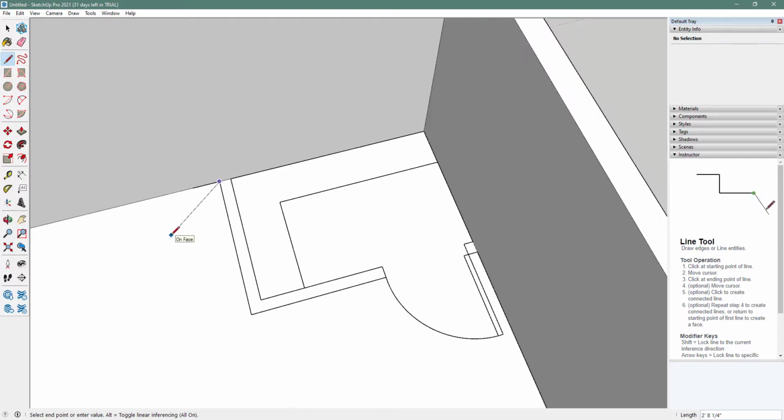That means you've started the line command, and then trace. Remember, we're not here to put in doors yet. We're just doing walls. So continue until you hit the wall. Make sure that you got that purple circle. Make sure that you continue to draw and see how it's red. That means I'm drawing perfectly on the red axis, or parallel to it, I should say. And then we're going to end it back here. Now I don't need to retrace where the wall and the floor meet because that already creates a boundary. SketchUp, like I said, is kind of smart, so it knows that there's a boundary there.